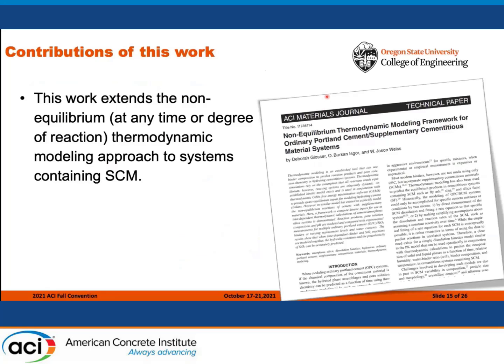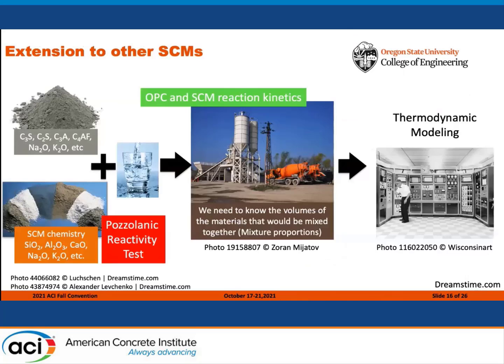This discussion brings us to our contribution. Our work extends the non-equilibrium, in other words, time-dependent thermodynamic modeling approach to systems containing SCMs. In this work, we incorporate unique aspects of SCMs that make the prediction of reaction rates highly complex. So what do we want to do? We want to predict, using thermodynamic modeling, the reaction products of a known amount of OPC with known composition and known amounts of SCMs with also known compositions.